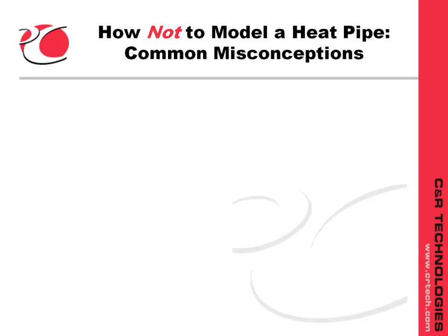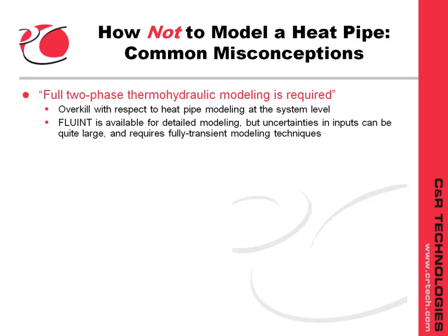For example, it isn't always possible to design using steady-state extremes, especially for variable conductance heat pipes. But for an engineer integrating the heat pipe into their system, the heat pipe user in other words, that perspective is different. They need tools to verify that the designer has done a good job, that thermal gradients are as promised, that there are no transient conditions under which problems arise, and that the heat pipe hasn't been over-designed either. It turns out they don't need to know the gory details of what is happening inside the pipe in order to do this integration and verification task.